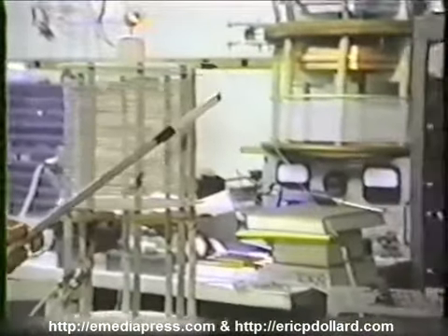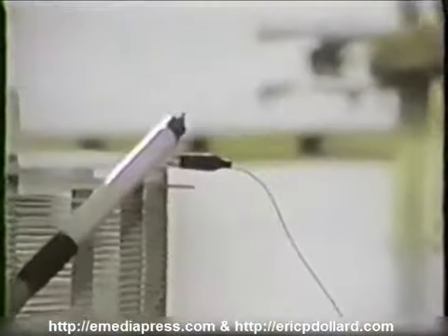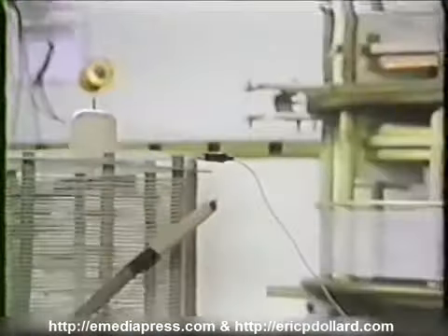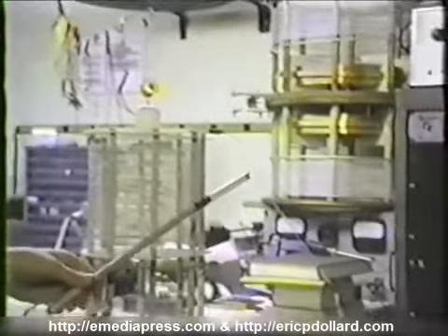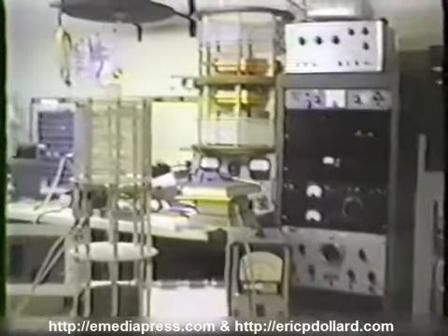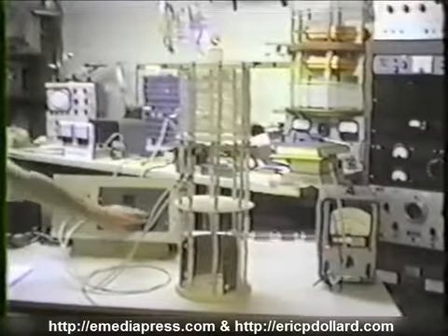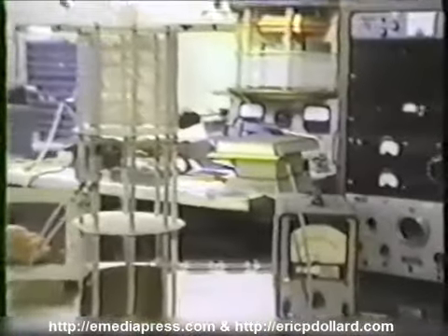And then our capacitive pickup is just a clip lead clipped on to the so-called insulating part of the coil. So we have a very light coupling between the end turns here and the probe wire, which of course goes to our same voltmeter. So what we'll do is we'll sweep around with the oscillator again and find out what kind of resonance characteristic we have here.